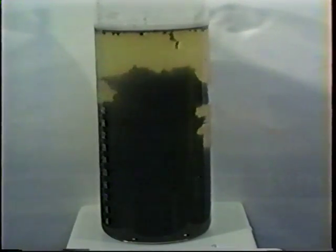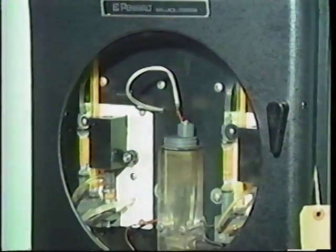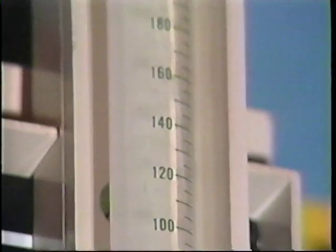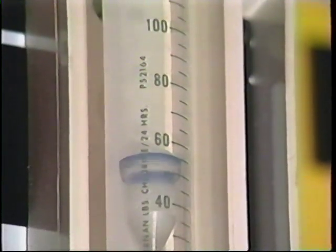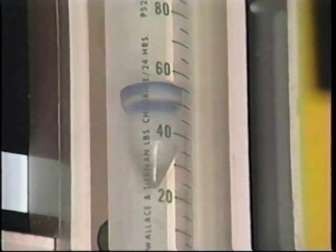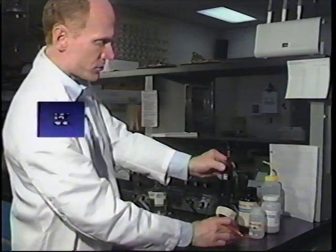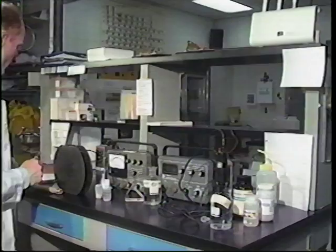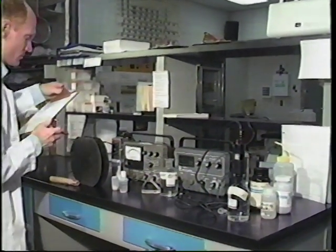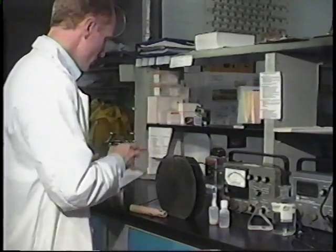For wastewater that exhibits septic conditions, the use of oxidizers such as potassium permanganate or chlorine may help to freshen the wastewater, reduce odors, and oxidize objectionable pollutants in the wastewater. The facility NPDES permit specifically requires the operators of the treatment plant to be familiar with operation and efficiency of each treatment unit. To meet this requirement, operators must perform and analyze process control tests.